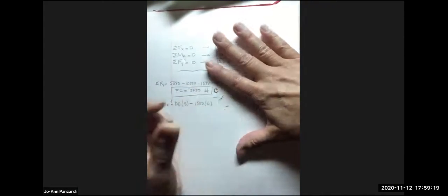It's easier. Sum of the moments about F. So it's DC times 8 positive, 1,000 times 6 negative, and 5,000. Nope. See, it's a lot less work. So DC turns out to be, what did I get for DC? 750. Matthew, it's positive. So tension or compression?